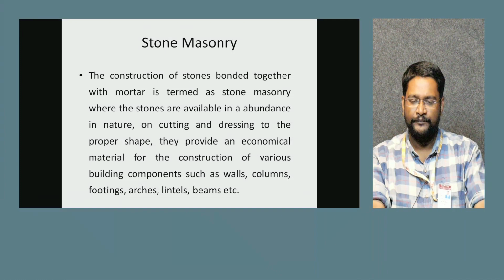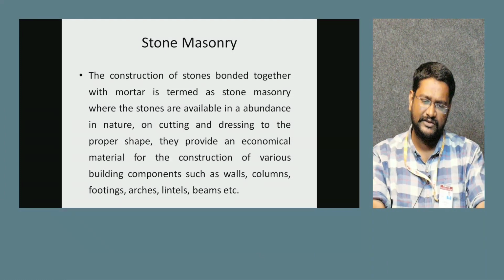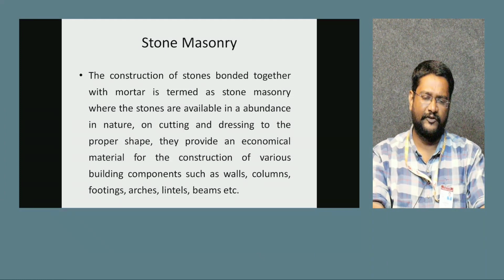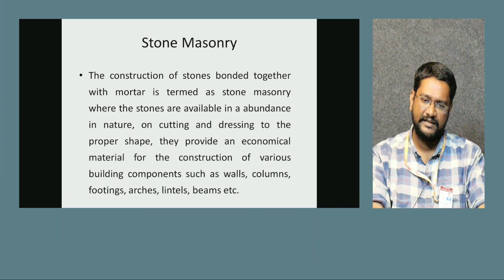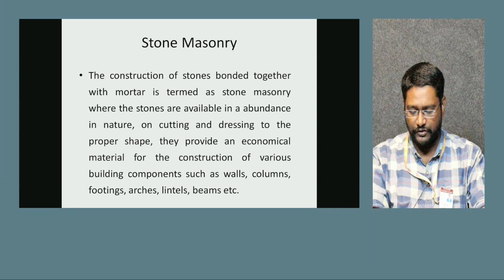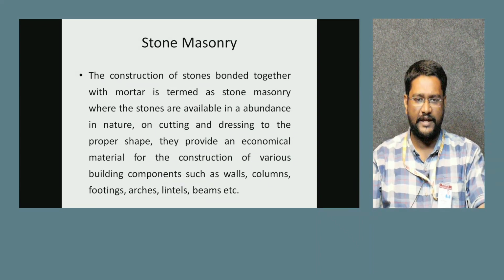So hills will be dug for the stones. The big boulders will come first. After that, whatever desired shape you want, you have to go with the crushers. We have to cut the boulders into the required shape and size of the stones. Those stones we can use for the masonry construction.